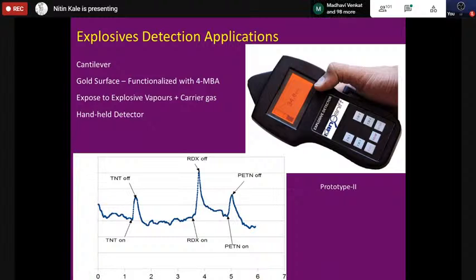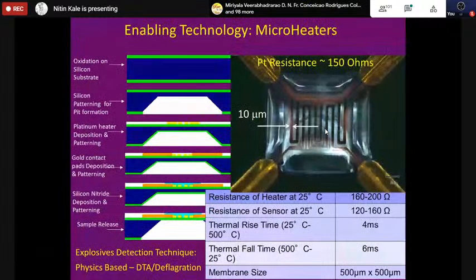However, our technology faced a certain problem: this particular thing was not highly selective, in the sense that it responded to a lot of other things. For example, to shoe polish, to various perfumes, to attar, and I think sometimes even water vapor. Now that was a problem, because with any good sensor, the selectivity also has to be very high. So we shifted onto a different technology.